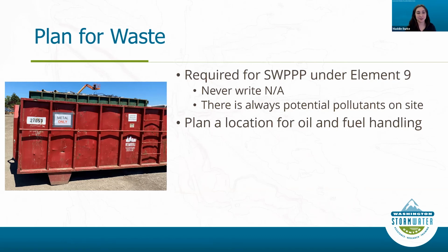But there's lots of common pollutants on site. Anytime you have vehicles, there's a potential for oil spills or hydraulic fluid. There's always sediment, and there's typically concrete or saw cut slurry, just different things to consider. There's going to be waste on your site, so this section should never say NA.